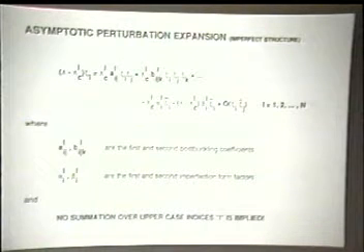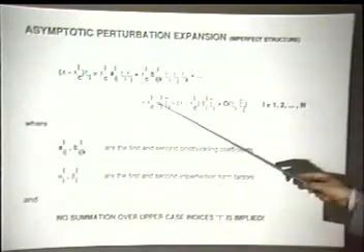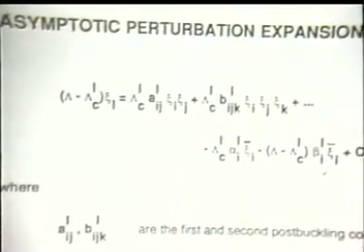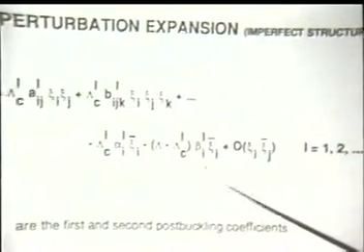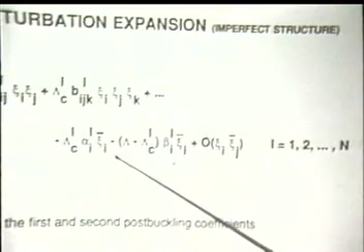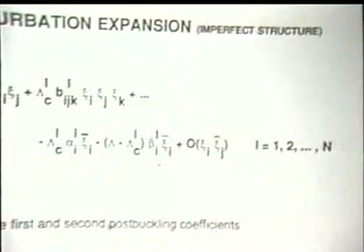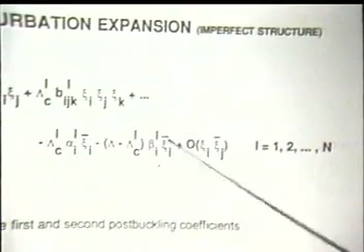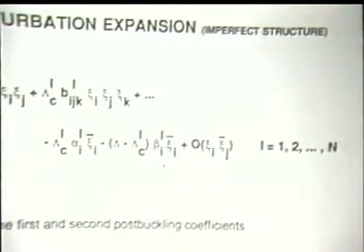But it could be that you measured the imperfections and they have a certain form, and that doesn't agree with the form of the buckling mode. You still want to use Koiter's theory. You can. But then, when you calculate the coefficients alpha and beta, they will not be 1. They will be some other number. Essentially, this idea of introducing the first imperfection form factor was done in that paper by Hutchinson and Frauenthal. And the second imperfection form factor was introduced by Cohen when he derived his code SRA.